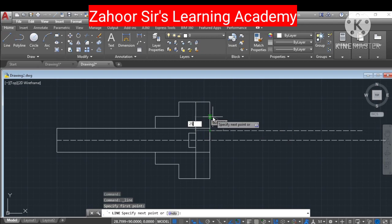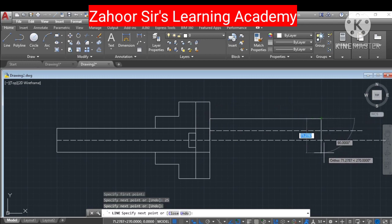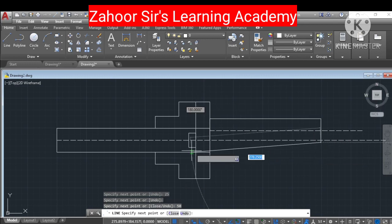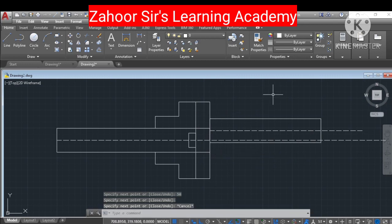So I will write 20 mm, then enter, and then I can go to this end as much as I wish. I will drop it there, then I will go 50 mm down because the diameter of the shaft is 50 mm. So 50 mm, then connect this with this one, and drop it there. So this is how we have drawn it.